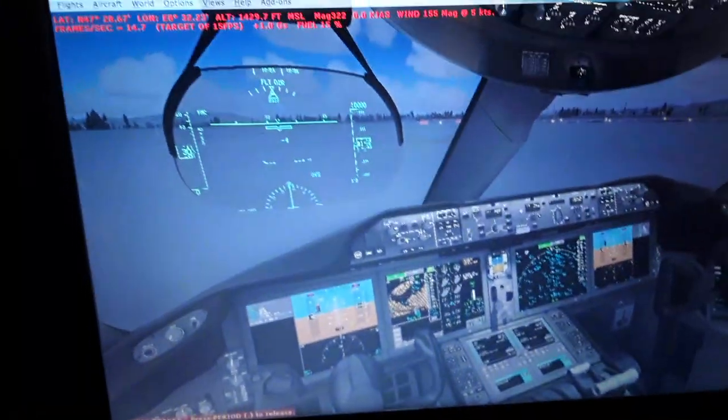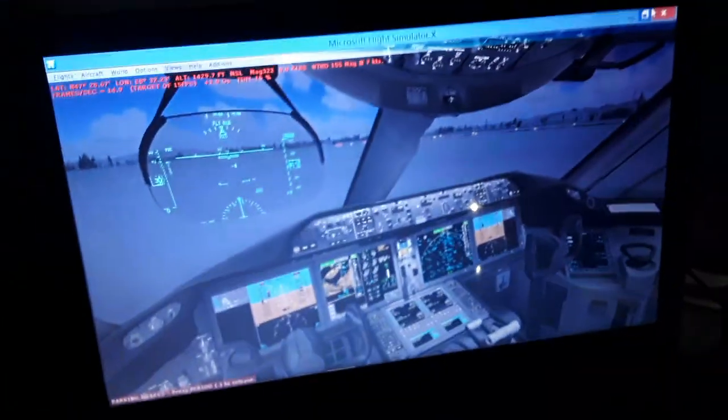We're also going to have 30-35 degrees of flaps extended for approach and landing, at an airspeed of about 160-170 knots, or 270-300 kilometers an hour. And we're going to have the landing gear extended, thrust levers and engine thrust at 60-70%, and pitch of 9 degrees or less. So I'm going to show you how we set up the flight plan in the flight management computer.